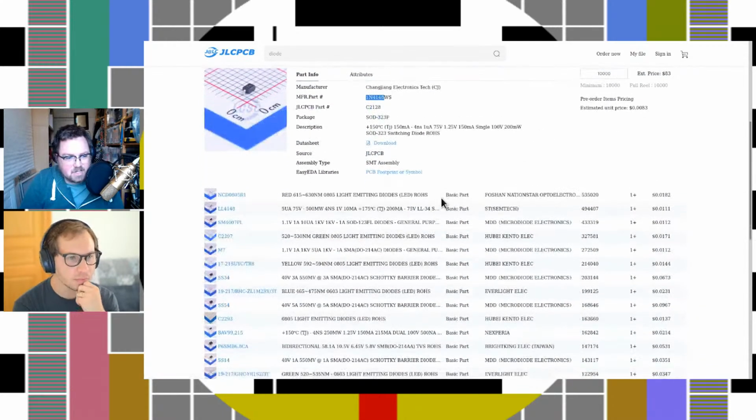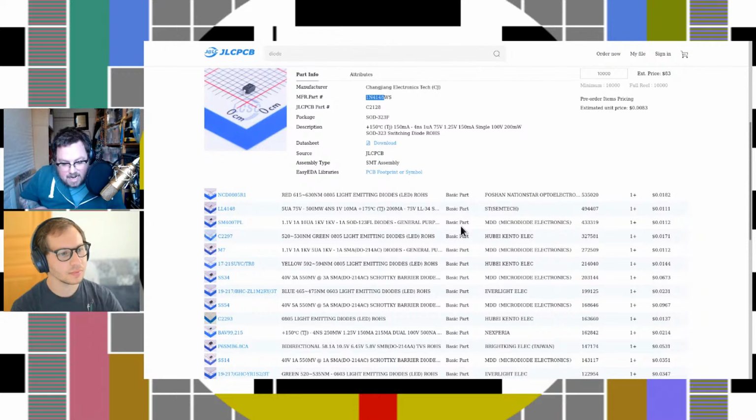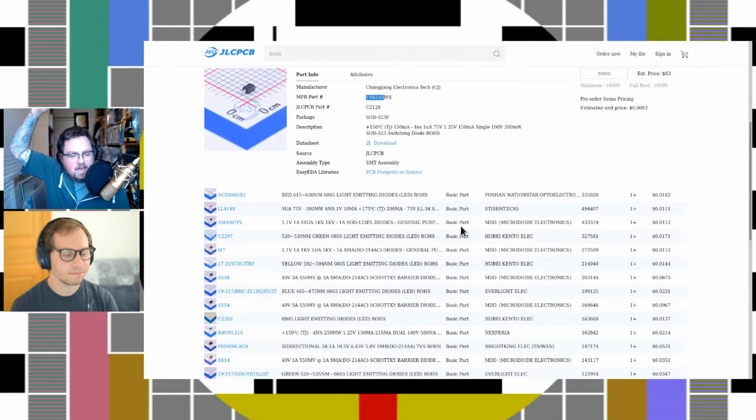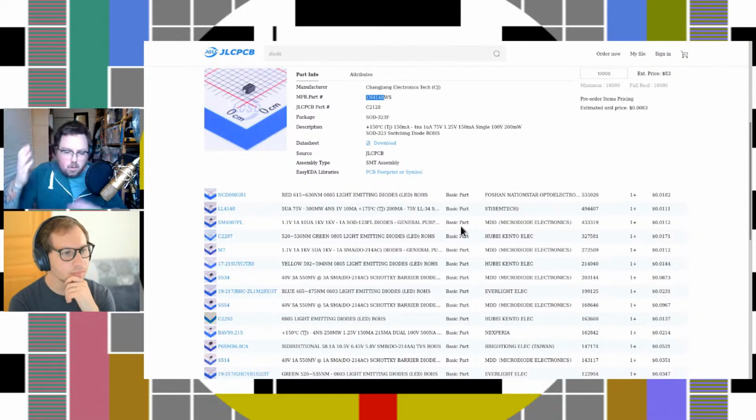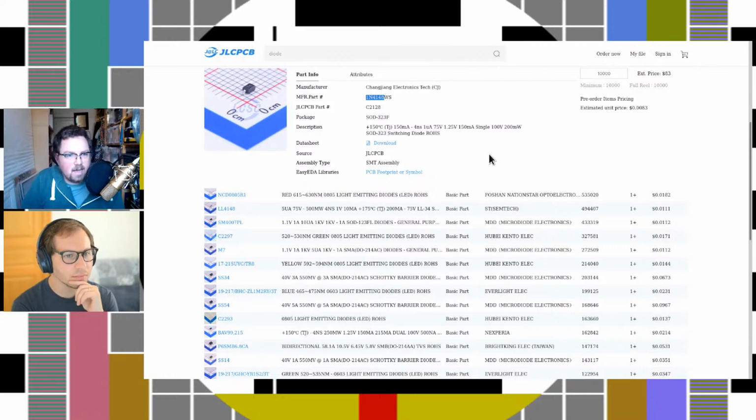But a lot of the time, for just the first filter, I'll use diodes that I use in other designs. Like if I use something in another design, I might just go look at that and be like, okay, well, how fast does it have to be? What does the voltage level need to be? Like if I'm using it with a 3.3 volt microcontroller, will it act like a diode at that voltage? Or does it only work for like 9 volts or more or something like that? And a quick look at the data sheet will give you that.